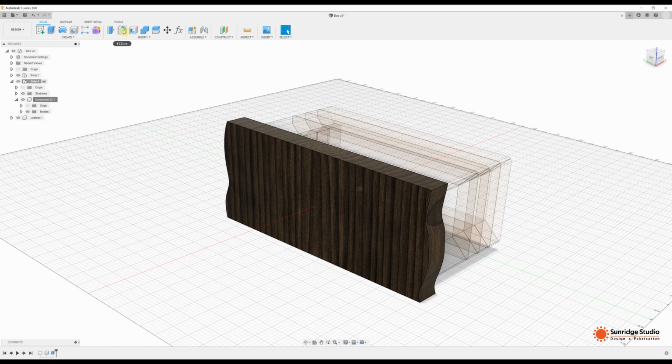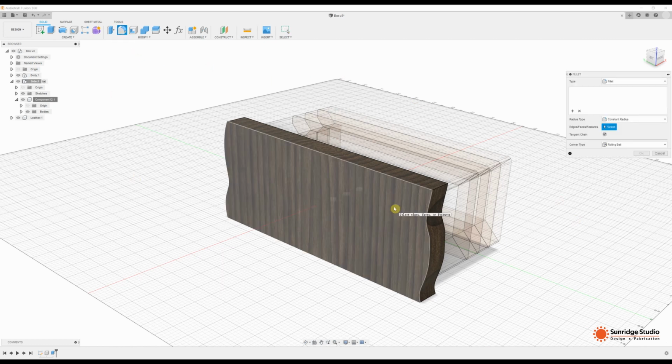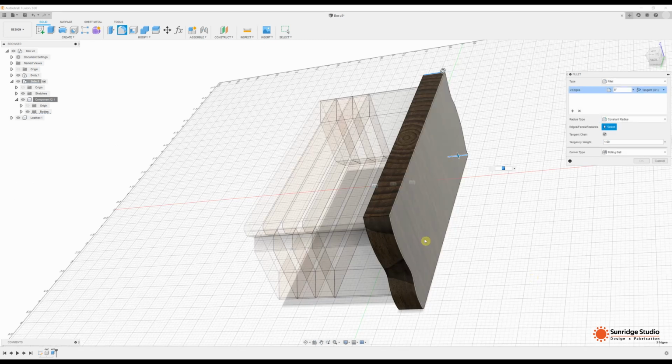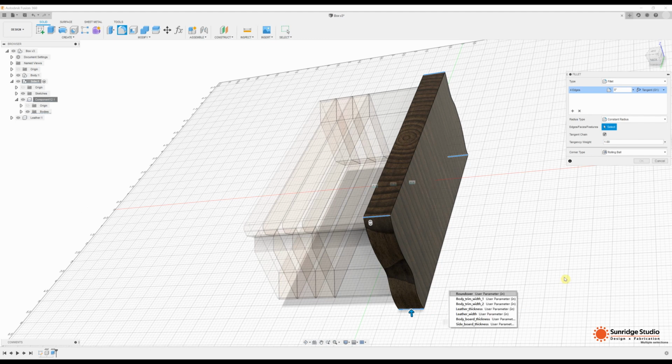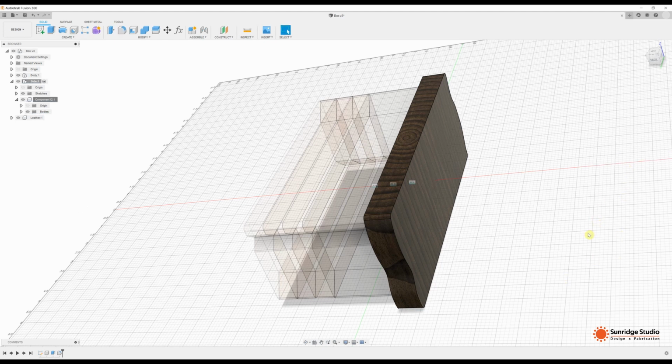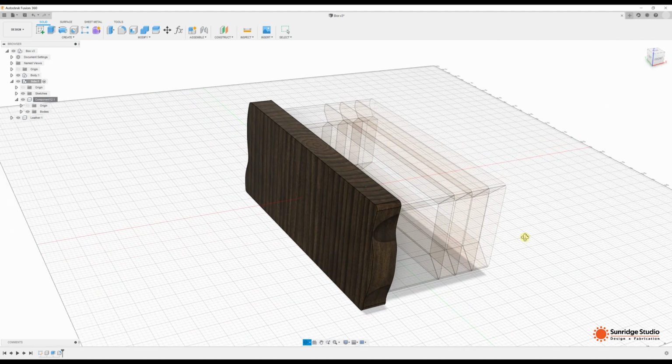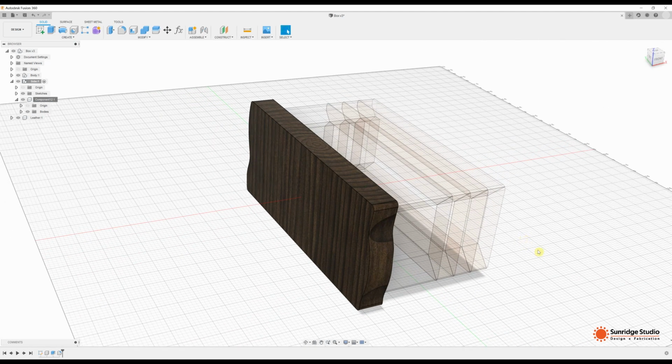And then we can use the fillet tool to give the four corners a slight round over. So we select the four corner lines and then use the round over parameter we set before. Yeah, so basically that's the seat board. So we save the current progress.